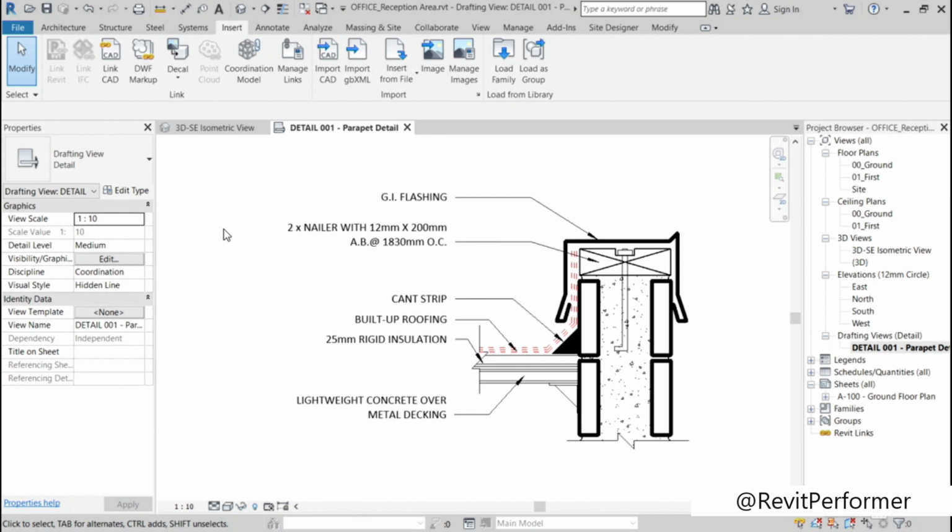Now, you don't have to change everything in your Revit projects to a different font and a different height, but in the details, sometimes a smaller height font with a different kind of text like Calibri or perhaps something other than Arial helps them stand out on your detail views in your Revit projects. It's up to you, but you can see what a difference that makes when I bring that down a size and change the font of the text in the annotation. And again, that might be consistent with your AutoCAD standards in your AutoCAD drawings as well. So it's always worth bringing in those settings into your annotation families in your Revit projects as well.